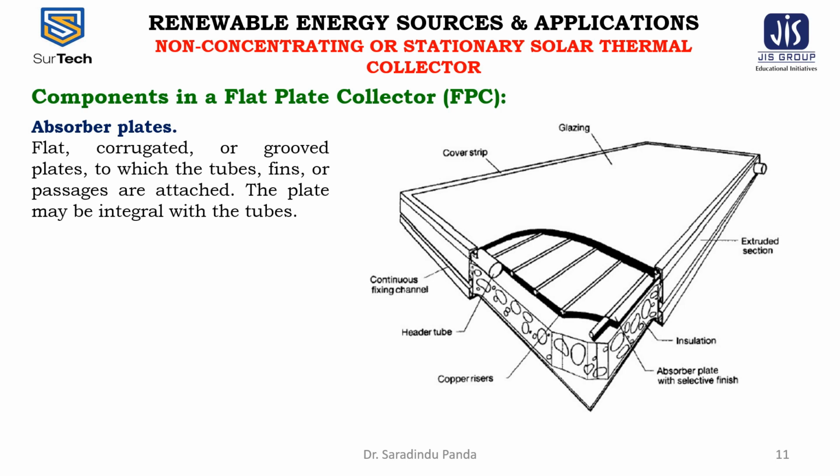Another alternative is to coat a non-selective, highly absorbing material with a heat mirror having a high solar transmittance and high infrared reflectance. Nowadays, the commercial solar absorbers are made by electroplating, anodization, evaporation, sputtering, and by applying solar selective paints. Much of the progress during the recent years has been based on the implementation of the vacuum techniques for the production of the thin type of absorbers used in the low temperature applications.